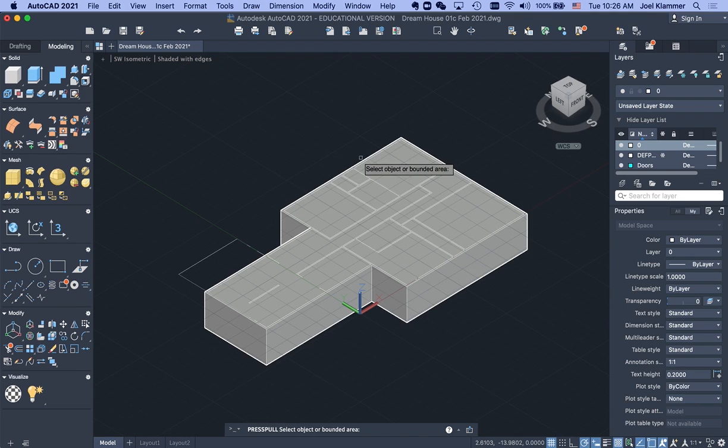But for example, I'm going to choose this bedroom back here. Notice that it cleans that outline. I'm going to click on it, and now I'm going to move it downward. Now 5 meters is all the way to the bottom. I actually want to leave a 0.5 meter foundation below our house. So I'm going to only extrude or push-pull our rooms 4.5 meters downward. And at this point, you should be able to see, oh yeah, look, I've got a hollow space right there.